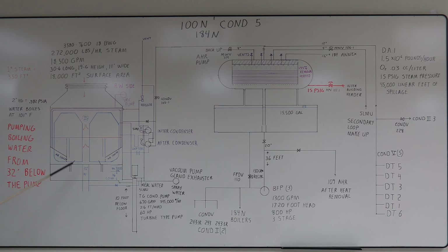So you have like minus 14 pounds pressure here. It comes up around 30 feet or so, 31 feet. The water's boiling. If you're trying to pump water 32 feet up, it'd be impossible. So that's why you have to try and maintain the pressure here, same as here, so it sees the weight of the water. That's why there's a vent line to move any non-condensable gases back here.